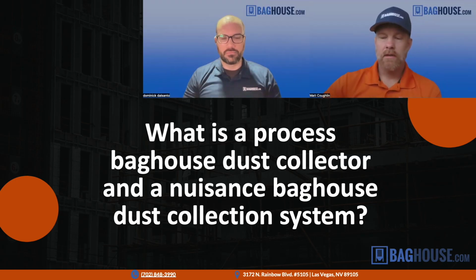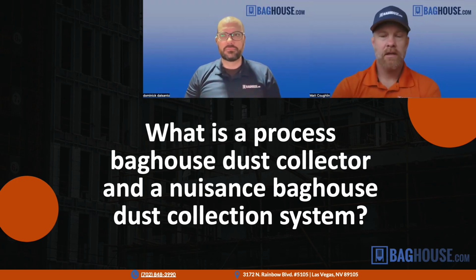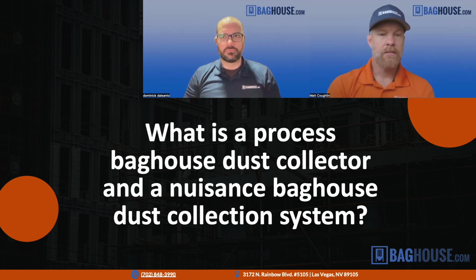Yeah, so a process dust collector, a process baghouse, usually means that it's part of the process. So rather than just collecting dust that you want out of the building, out of the way, it's collecting something that's going to be either recirculated back into your process or used in your process.